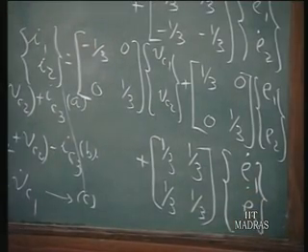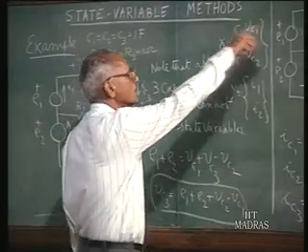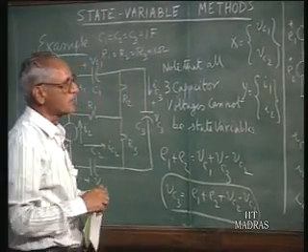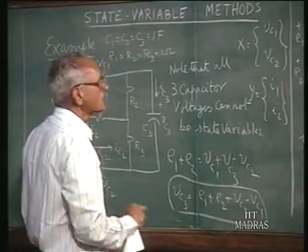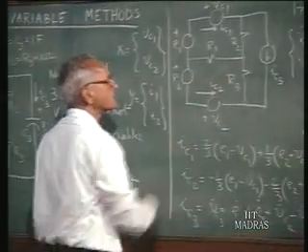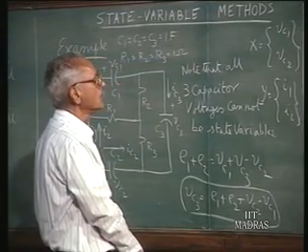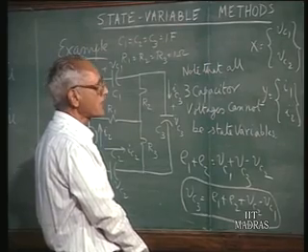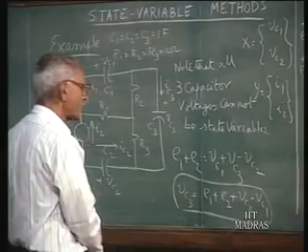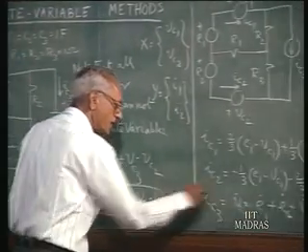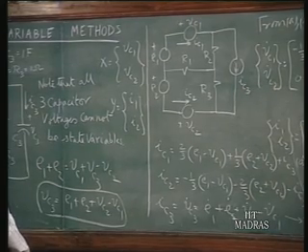So that's how you can obtain the extended form of the state and output equations once you have source and capacitor loops. So all the principle that is involved is that the excess capacitors are replaced by current sources, and you write the equations in terms of the source strengths, state variables and the additional current sources, and the current sources are eliminated by writing out an extra equation for the current source strength in terms of the derivative of the excess capacitor voltage, which in turn can be expressed in terms of the sources and the other